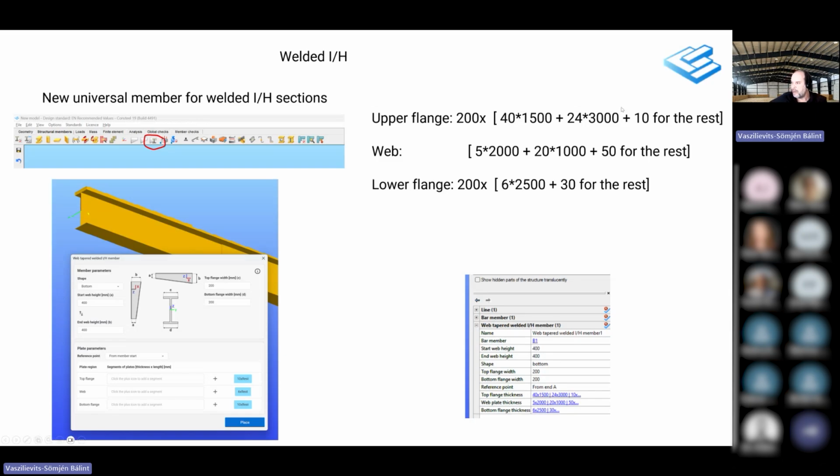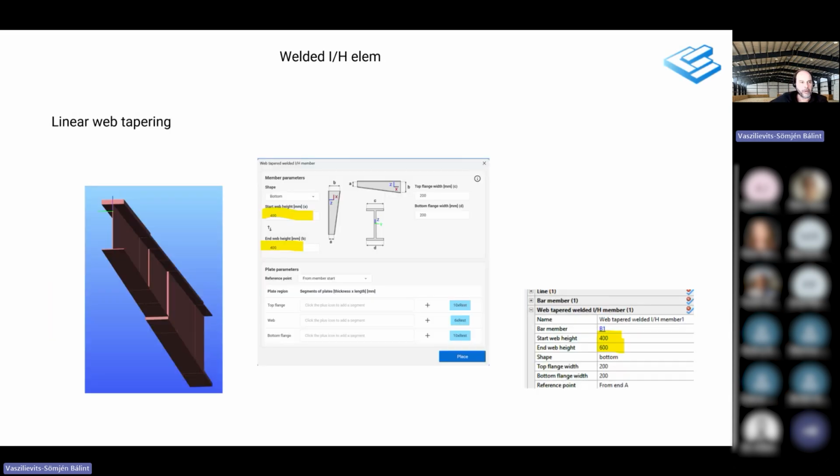That's up to Consteel. I just give this table to the member, and I can freely change it. I can add new elements inside. I can delete something inside. I just update the table, and once I click OK, Consteel will automatically update the model accordingly without me having to spend time on it.